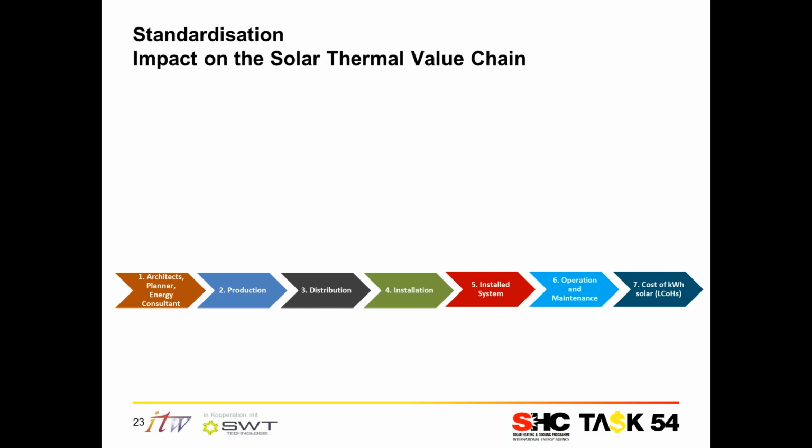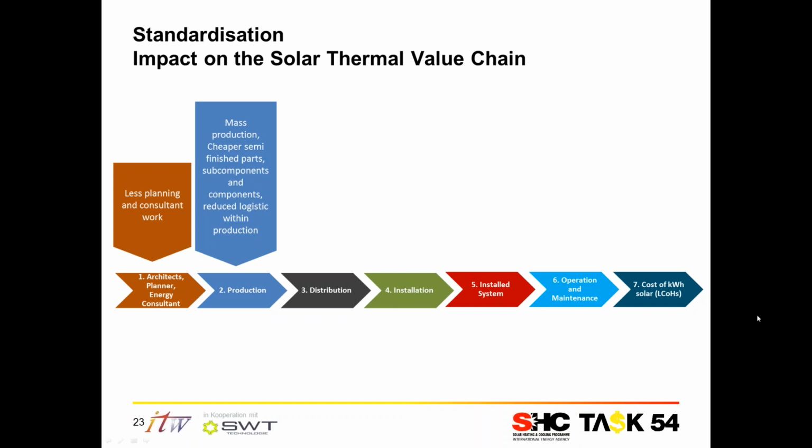So what will be the impact of the standardization on the solar thermal value chain? First of all, if we have standardized components and maybe also standardized system concepts, then there's less planning and consultant work needed. During production, we have the possibility for mass production. This will cut down the costs for the semi-finished parts, subcomponents, and components, and also result in reduced logistics within the production. During the distribution, we have a reduced effort for packaging, storage, and transportation, because a lot of the components are standardized, so the same packaging can be used